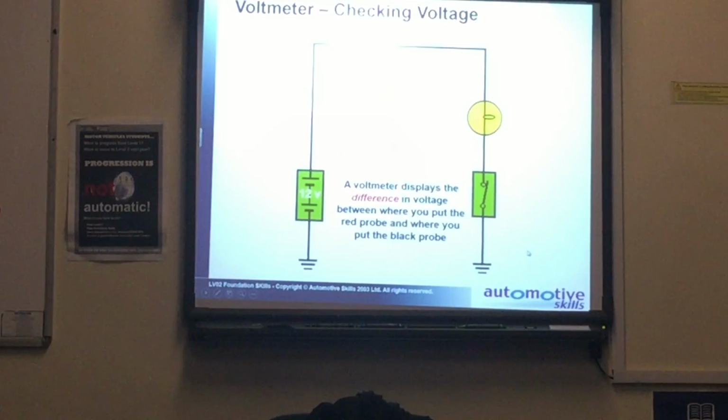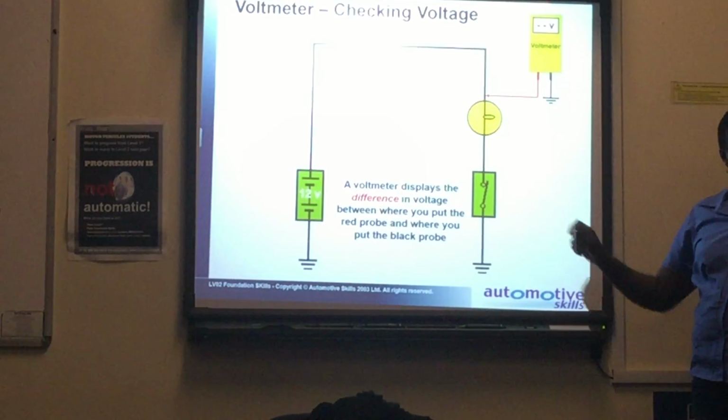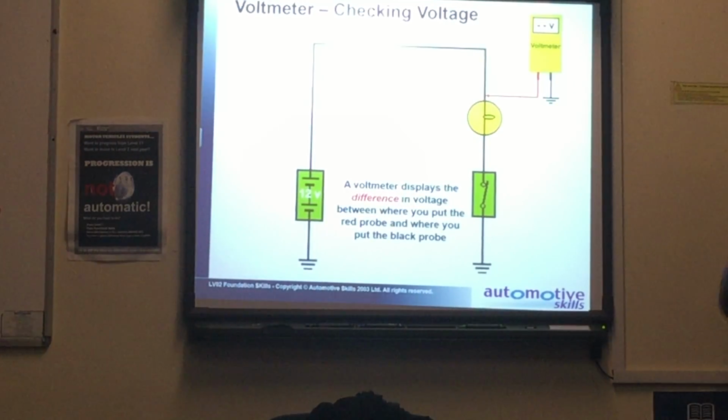After the fuse, we can still get a reading. Before the bulb, so it's always the positive. You are just playing about, this one is negative all the time on the body. Then you get your readings at several places. That is voltage. Are we clear with that?